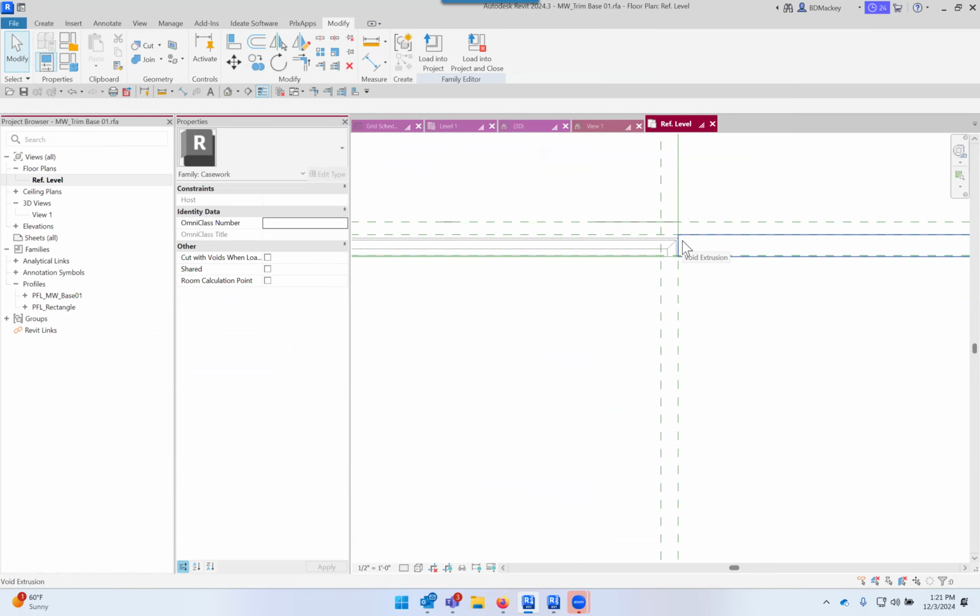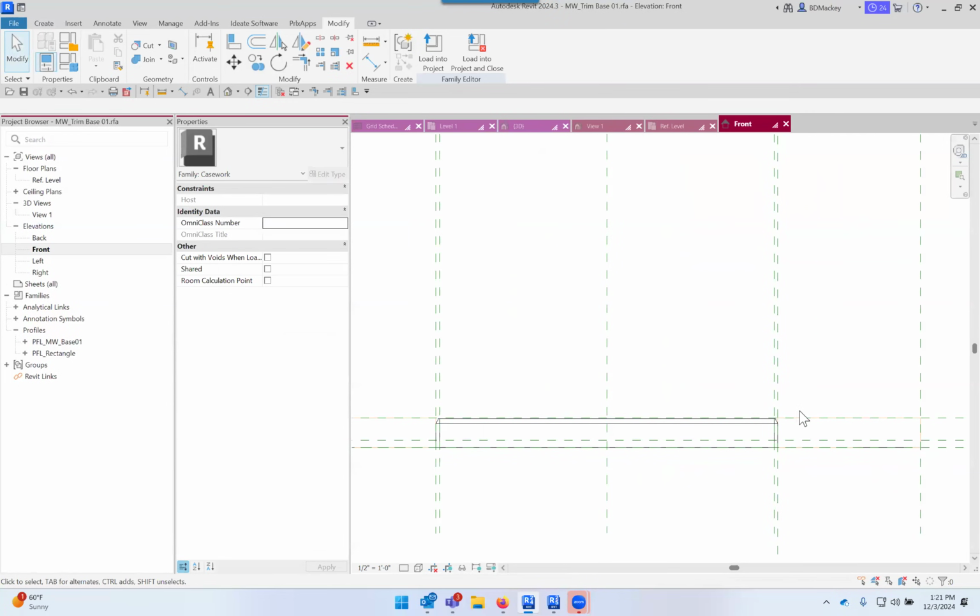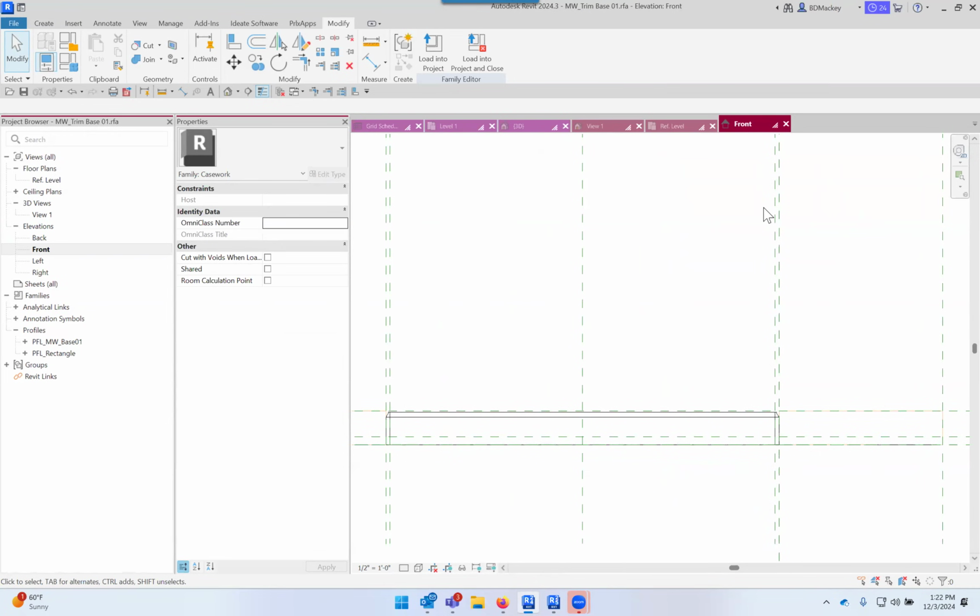Because again, even if I were to try to keep that plumb, thinking in an elevation type scenario, it's not going to do the same thing. And I believe I also have a vertical one. This might be an older version. I believe on some of my families I've done the same thing. So if I nest that, then going vertically, I can do a 45 this way. So I've got different voids nested in different views to cut it at different angles.